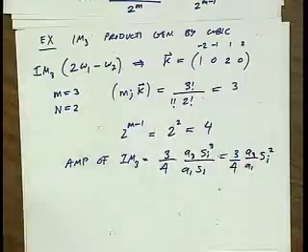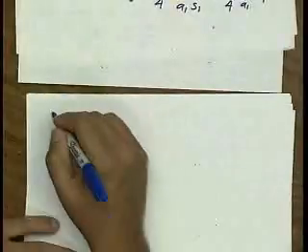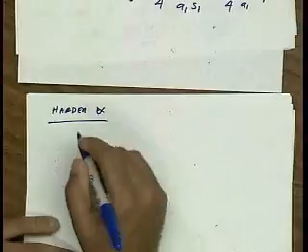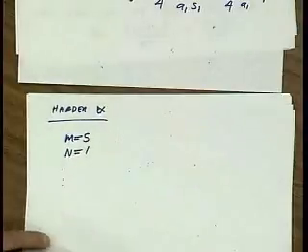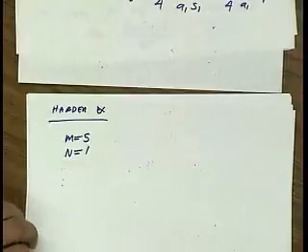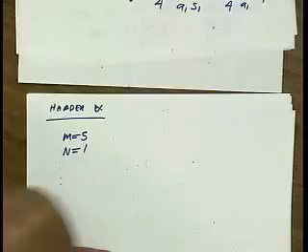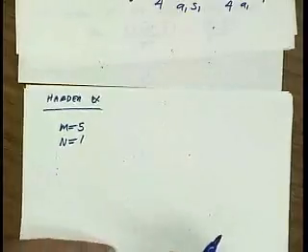Okay, so this was an easy problem. We already knew the answer, so it's nice we can derive it another way. Let's do something that would be excruciatingly difficult to derive by hand. So let's do a much harder example. Let me take m is equal to 5, n equals to 1. So just one tone, but 5th order. So you can do it by hand, longhand, right? You can take cosine to the 5th power, or we can use our result.